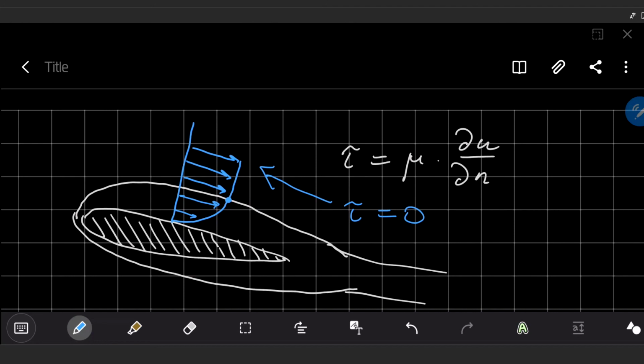And it's absolutely equivalent to the inviscid flow model. So if we do not have shear stress, we do not have the viscosity influence, and it does not enter numerically into the equations of the flow, we consider the flow inviscid. Even if we use the viscous flow model or complete Navier-Stokes equations, in the region outside of the boundary layer, shear stress is equal to 0.